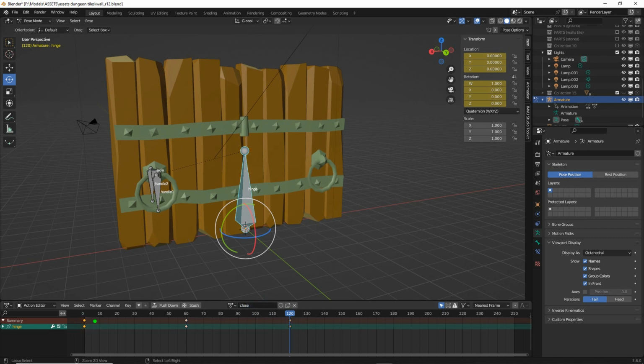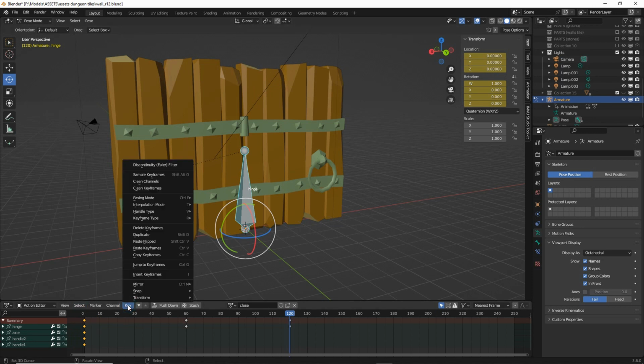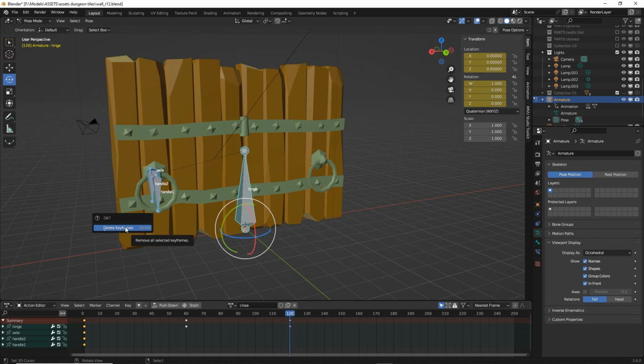We then need to select all the markers at frame 1, delete them, and then move this to frame 1. So let's just select all the bones, because remember that we set a base pose for all the bones. So at the moment, if we just delete this, all we're doing is deleting the pose that's associated with that bone on its own. So select all. So Alt click, that loop selects essentially that keyframe. We can now delete those. So key, delete keyframes.